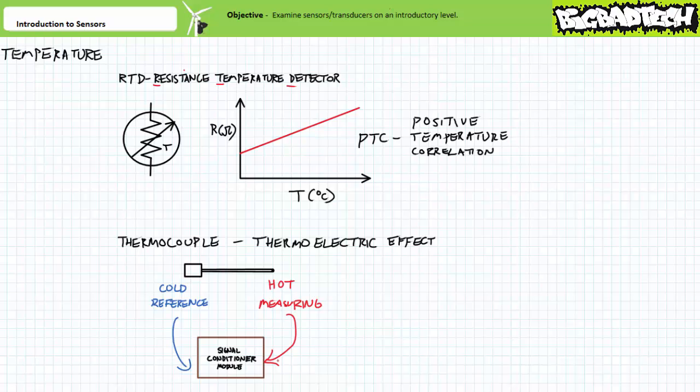Long story short, a sensor is not only a detection mechanism, but also a means of measuring a quantity. Via the transduction process, the physical phenomenon being measured, whether it is pressure, rotational speed, wind speed, flow rate, position, level, or temperature, is represented as a proportional voltage or current quantity. By adjusting the zero and span, an operational range can be established and appropriately scaled for the particular application.